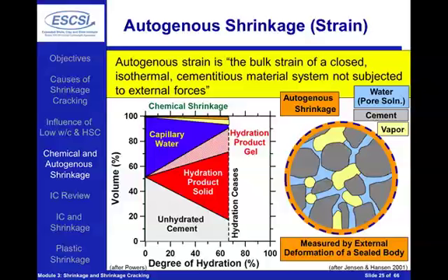Now, it's important to understand that this concept of vapor-filled spaces forming happens in every single concrete every single day, unless there's an infinite amount of water being placed at the surface of the concrete. However, these vapor-filled spaces become very, very important in lower water-to-cement ratio systems, mainly because of the size of the pores that these vapor-filled spaces can form in. If they form in large pores, generally they don't result in the development of a lot of stress. Therefore, you don't see a lot of external volume change.